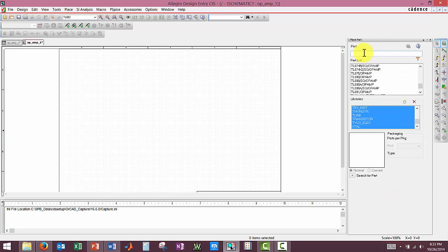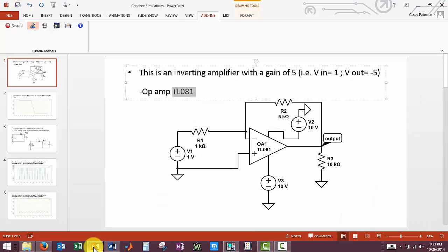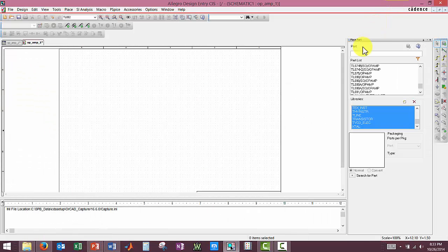So we are going to be searching for our op amp, and I'll pull it up here. This number, I'll copy it over, and Control V. We're searching for an op amp specifically with a simulation property, and that's very important. You have to have a simulation property. Although this is the TL081, it does not have a simulation property, which will be indicated down here. So I'm going to look for one with the right number of pins down here for us.